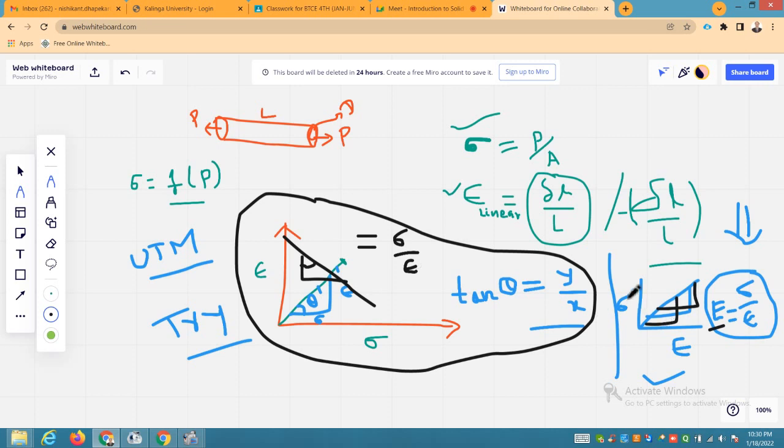So the assignment you have to perform in the laboratory is, if you reverse the plotting of the values of stress and strain like this or like this, how you are getting a straight line, how you are calculating or evaluating the slope, is the question.